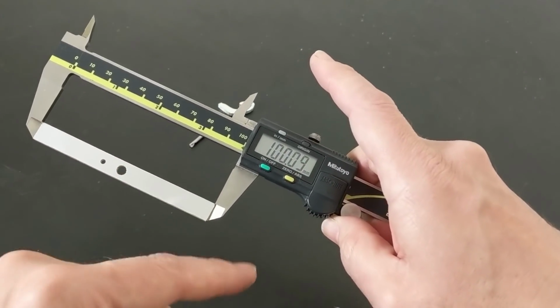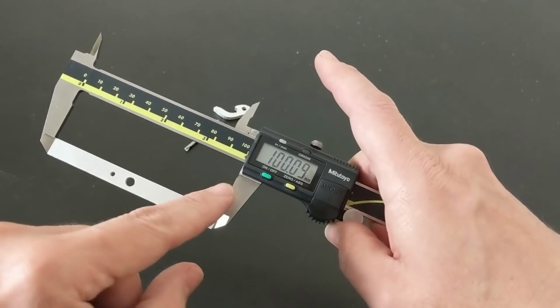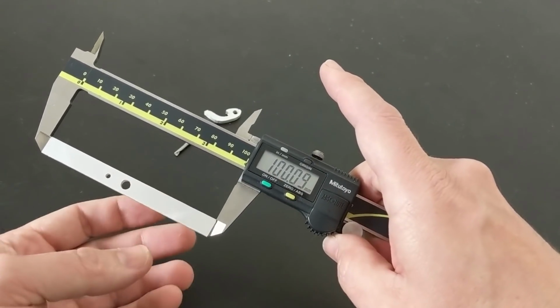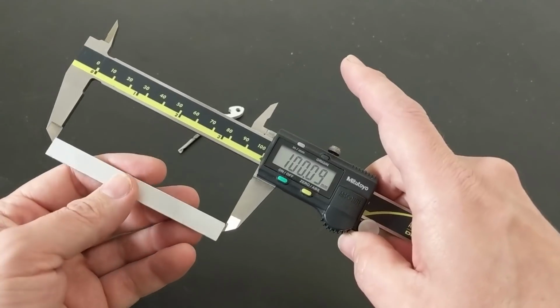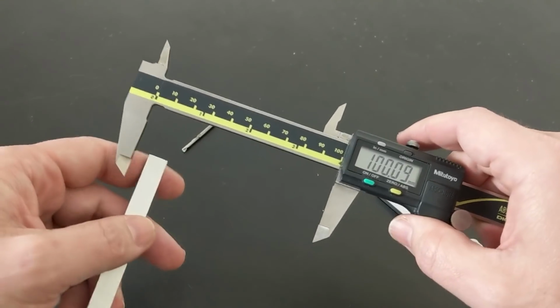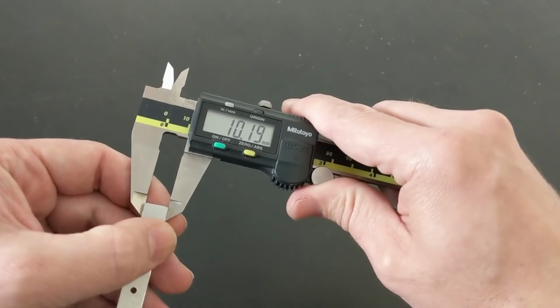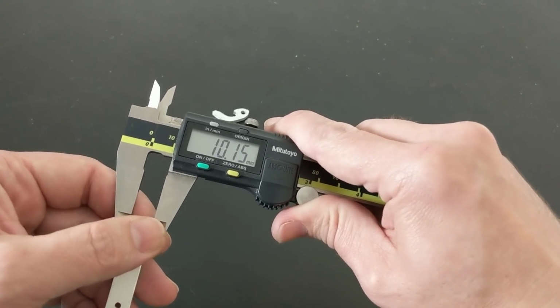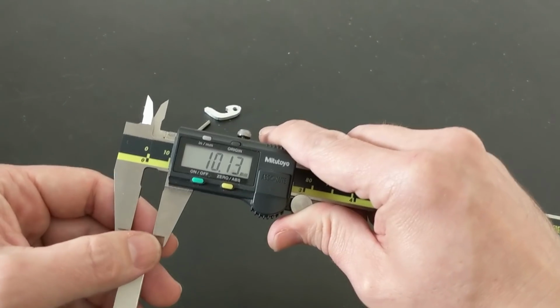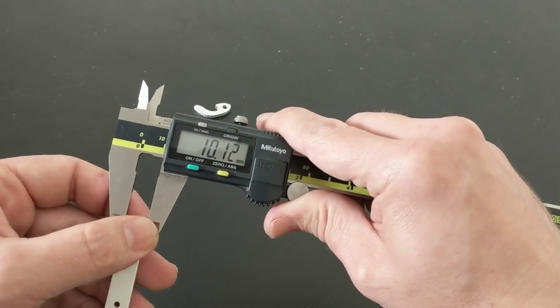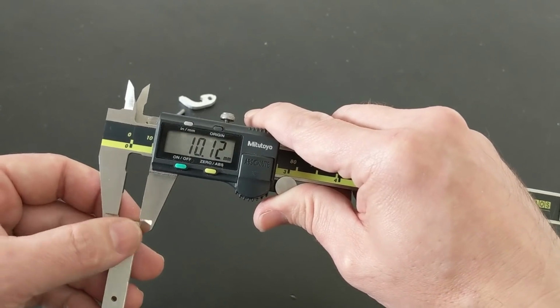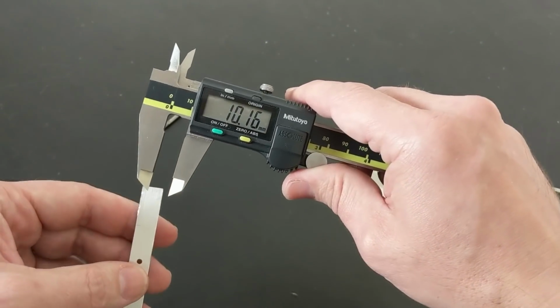Yeah, that's interesting. So basically that tells me that my machine is calibrated correctly with the steps. It's moving the correct distance, but that play there is all going to be in the bit itself, either flexing out of the way or more likely just slop in the machine, using lead screws with those flimsy little springs for the anti-backlash nut.